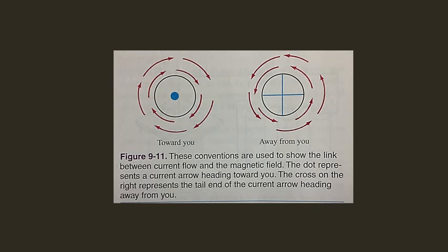This principle is very important when electrical wires carry alternating currents. This is because the placement of wires, or lead dress, has an influence on the workings of a circuit. Conductors are grouped in pairs whenever possible to eliminate heating effects and radio interference caused by the magnetic field created by the current flow. The National Electric Code requires that wires be run in pairs to help eliminate this heating effect.